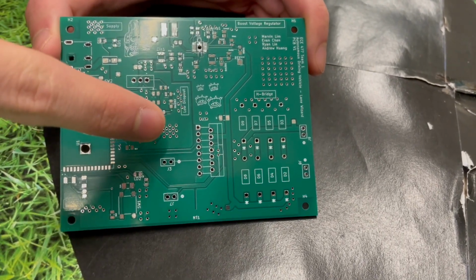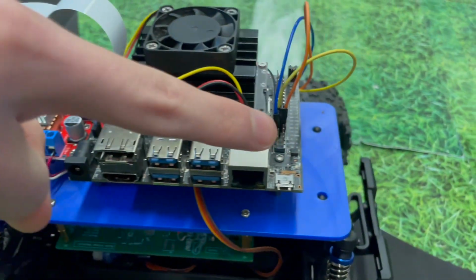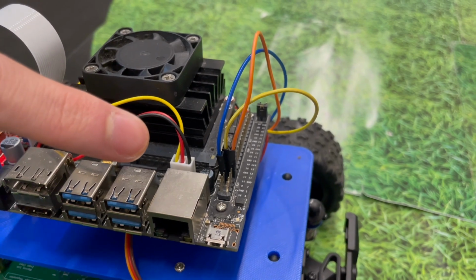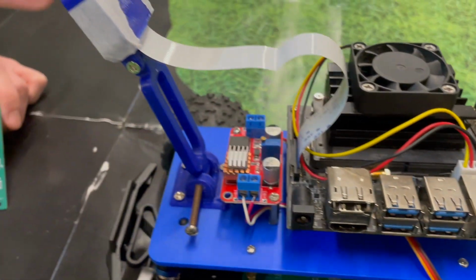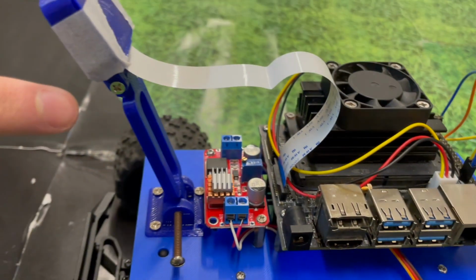the speed and direction. The Jetson Nano is connected to the microcontroller through UART to transfer the speed and angle predicted from the machine learning model we built. It is also connected to a Raspberry Pi camera that captures the view and predicts the lane in real time.